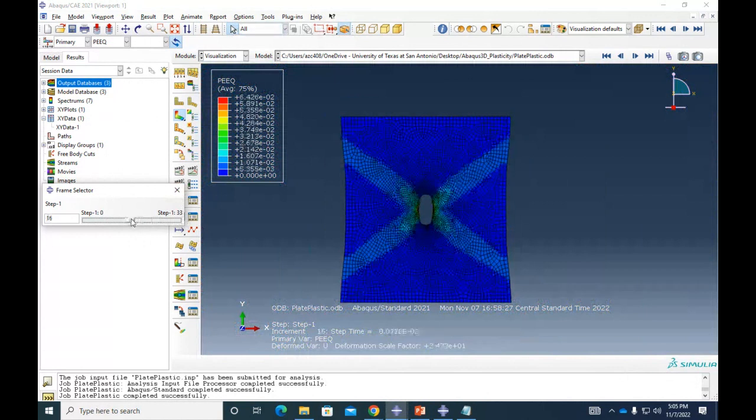All right. We could also add some heat transfer to this, but as you guys saw, it's super simple. What else can you do in heat transfer? You can add convection, right? For those of you who have had this thick pressure vessel, you want to see, hey, what happens if I have that pressure vessel in an ambient temperature that is super cold? I have it in a fridge. So you have your fridge temperature, and then you have this surface, and then you can see how much that cold air is affecting the results of your pressure vessel.